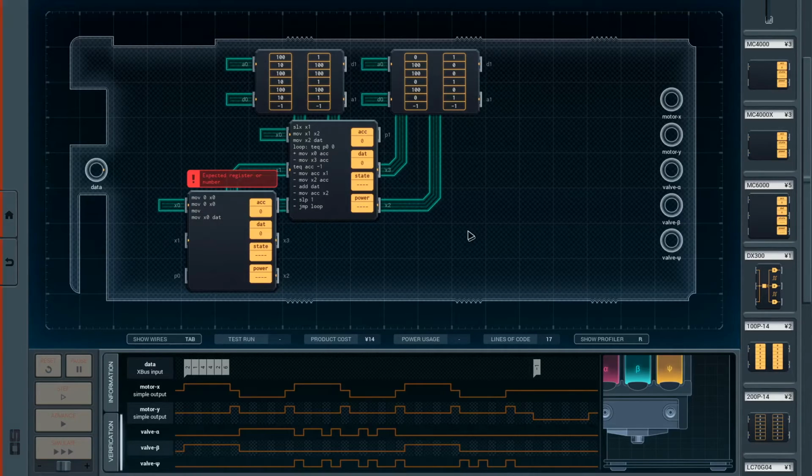Right, I'm going to just get a look at the data that comes back to me. Here, I'll do this more efficient for loop that I figured out. So move x0 dat, that's all. Just read that. Oh, hang on. Before I do this, I need to set the... yeah, okay, so set the simple pin, tell it the starting address, tell it which bank, or no, tell it the offset. Alright, so all zeros should read from this in forward order, right?